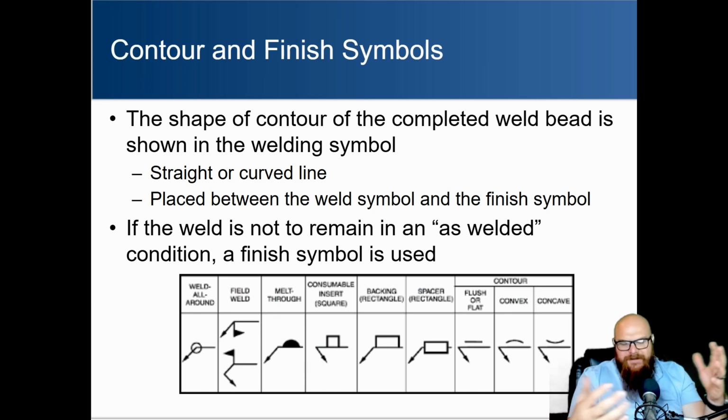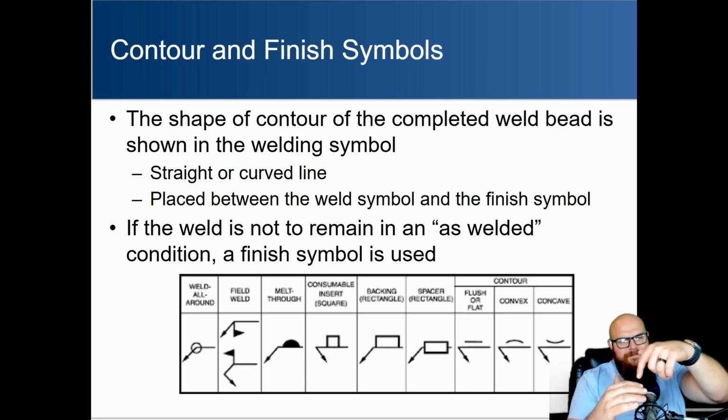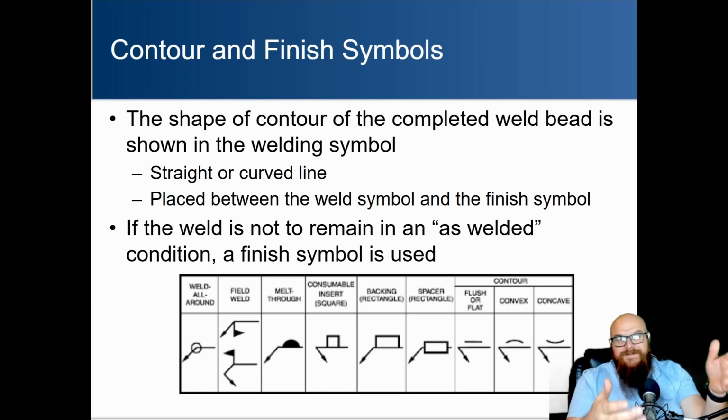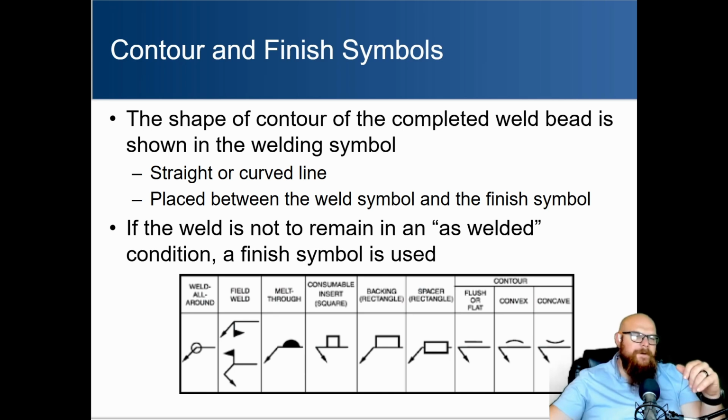You're going to indicate, obviously, it's going to be a fillet weld, but we don't want to weld just half of it. Especially on pipe where it's round, you don't really have one side versus the other. It's either do we weld it all around or not. So square tubing, you can kind of use that as well, because in a two-dimensional drawing, it's hard to get a three-dimensional aspect to it. And so the weld all around symbol is something that we'll see, especially on tubing, pipe, things like that.